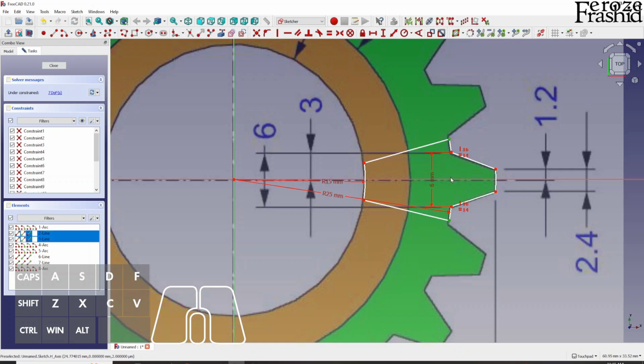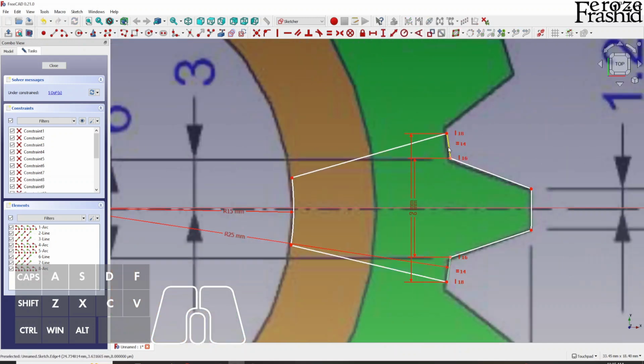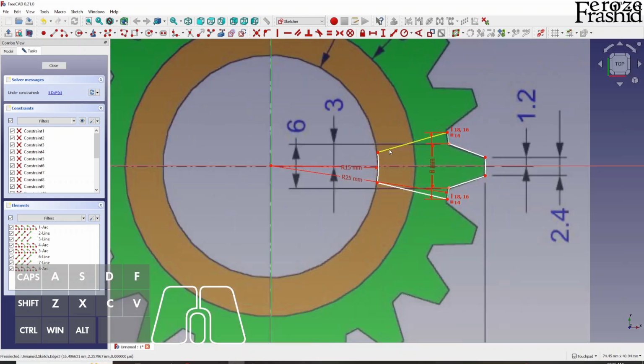We will just make that vertical, so that way they are symmetric, as we saw a couple of moments ago. Now I want to make the distance say 9. So that's more than half. If this is the half, it's passing the half, and that's what we want. I want to make this line radial, so it moves as a radius. So I want to take this point and this line and hit this button, constrain point onto object, and that way it makes it radial. Let's do the same on this one too.